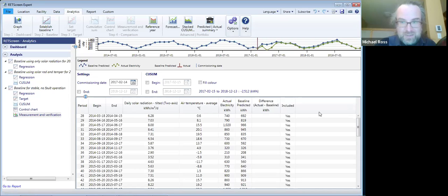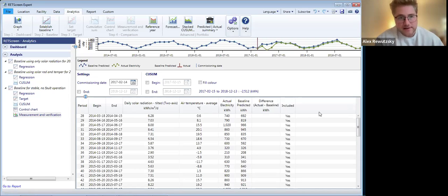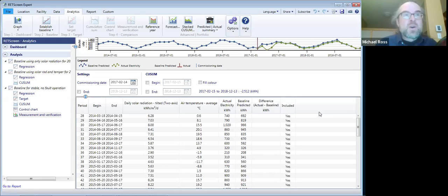The first one being, for sizing your PV system in terms of kilowatts, how would you do it based on available roof area as the input rather than defining the kilowatt capacity as the initial input? Yeah. So if you look at RETScreen's outputs there, it tells you the total solar collector area, which is based on the kilowatts of capacity and the efficiency. So you can pick the efficiency of your modules and then adjust the kilowatts of capacity until you get the roof area that you think you want to have.